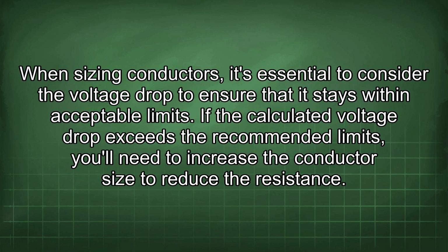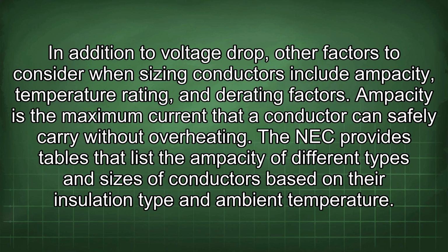If the calculated voltage drop exceeds the recommended limits, you'll need to increase the conductor size to reduce the resistance. In addition to voltage drop, other factors to consider when sizing conductors include ampacity, temperature rating, and derating factors.